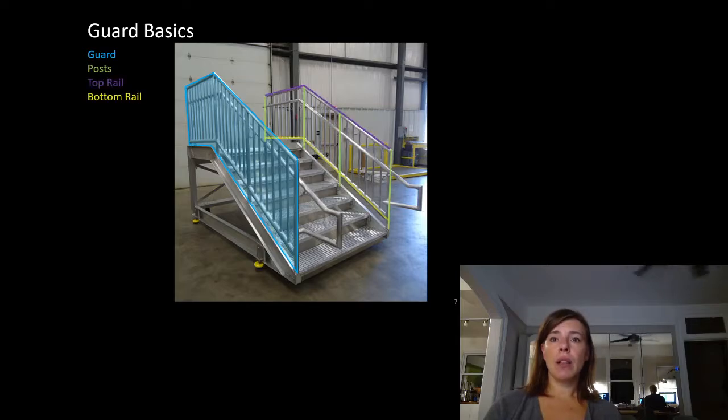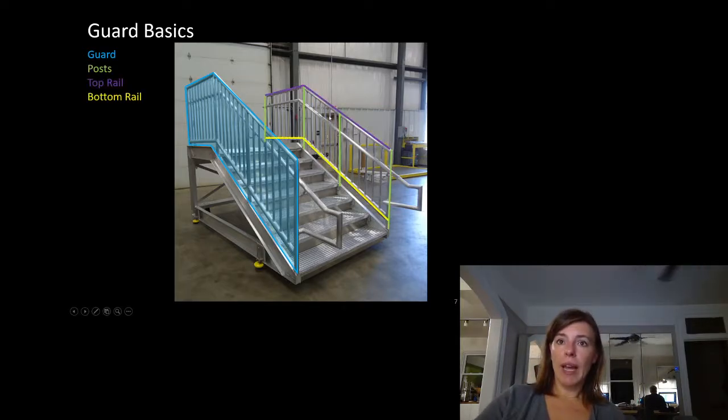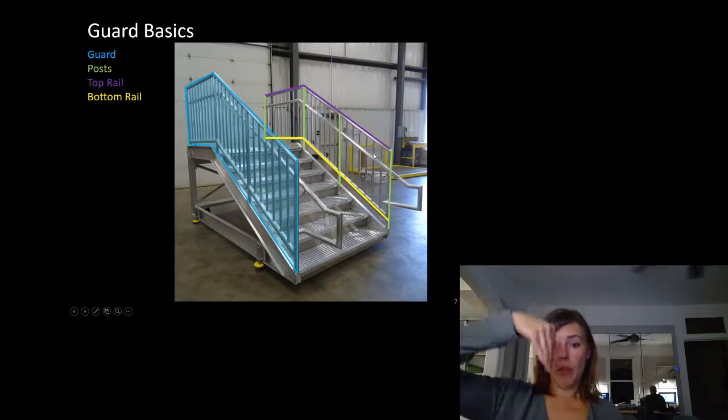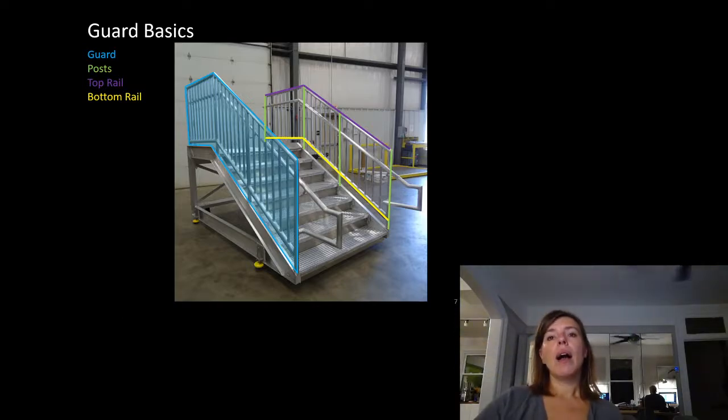Now the bottom rail might also be working coupled to make a deep beam with the top rail for that 1.5 kilonewtons per meter up and down. You know, a kicking force, it would want to be designed for that 0.5 kilonewtons as well.